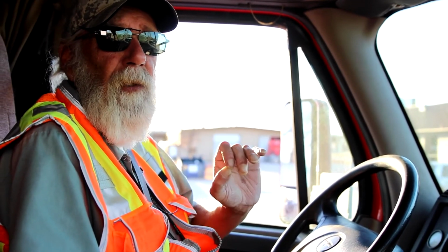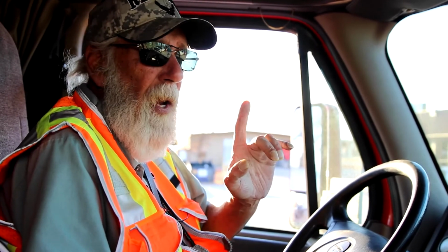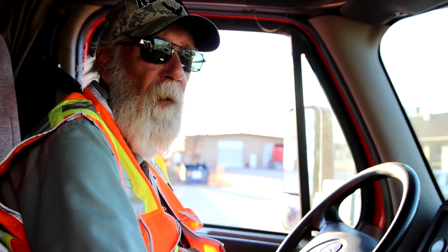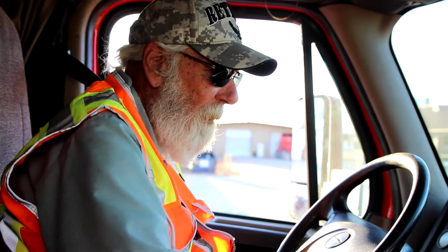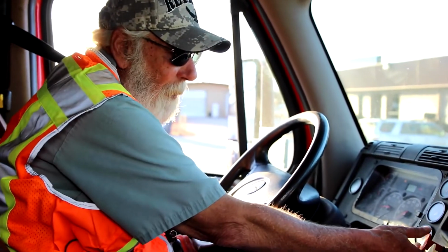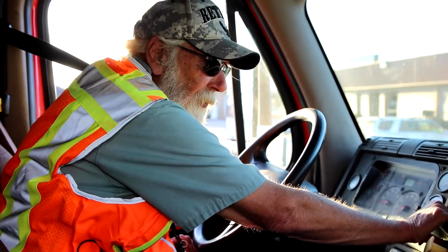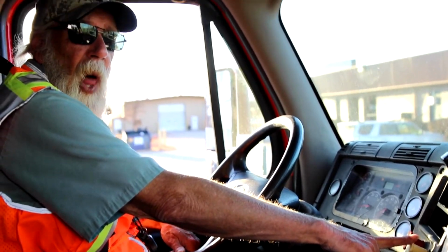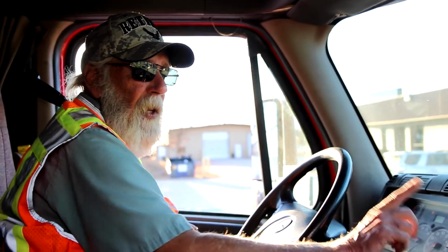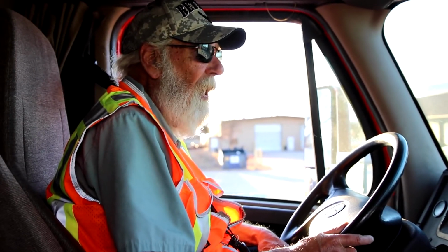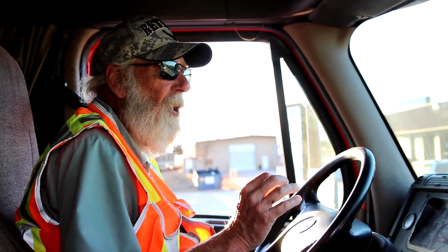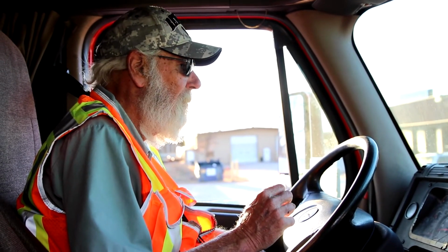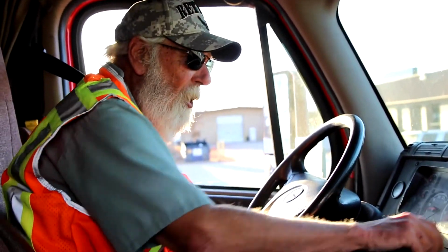The next part of my test is we're going to do a tug test against our tractor and trailer brakes. So we're going to place the truck in first gear, or low gear as some people call it, and I'm going to release my trailer brakes, which is the red knob. That releases the trailer brakes. And I'm going to tug against my locked tractor or truck brakes, and the vehicle should not be able to move, so give it a light tug. Do not jump off the clutch, just give it a light tug until you feel it. Just like that. The vehicle did not move.